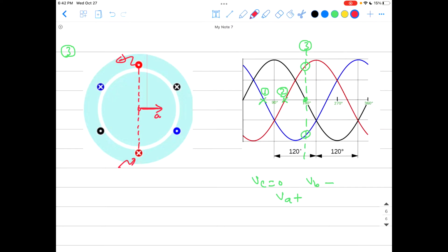That's the magnetic flux. And from B, the blue one, it's negative. That means the current goes into the dot, coming out of the cross. This will have a perpendicular magnetic field to it, but going this way. So this is coming from B. Okay, guys? The summation of those together will give you the resultant flux taking this direction. That is the third instant.